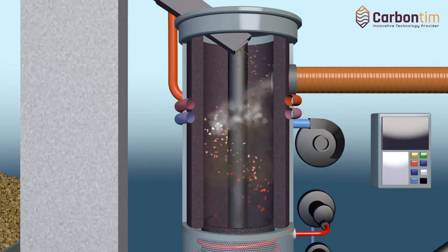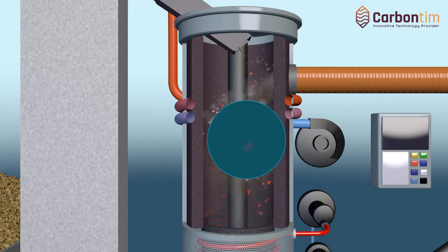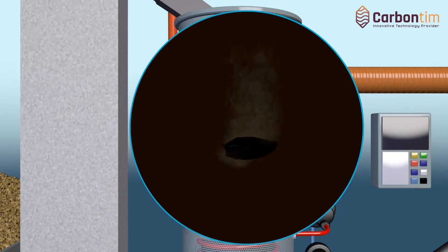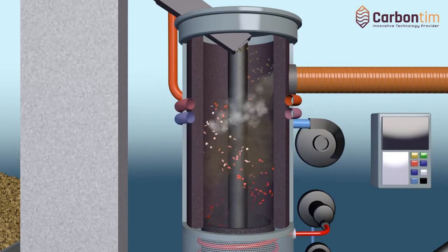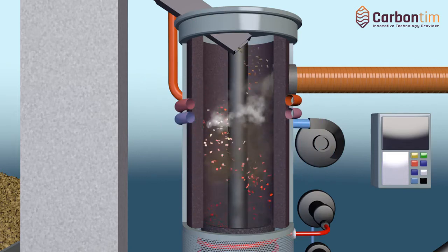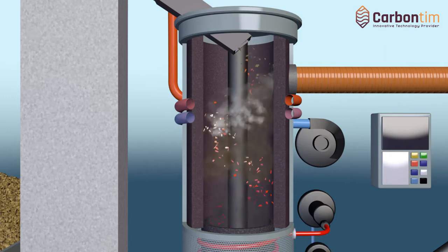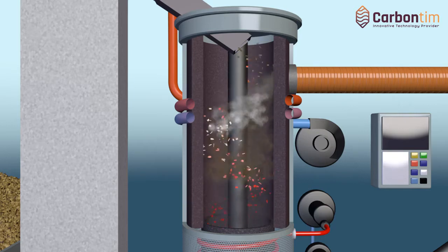The carbonization process. Dried and degasified biomass is treated with high temperature. This process results in the quick concentration of elemental carbon and the disappearance of the fibrous structure, improving its grindability. Depending on temperatures inside the reactor and the duration of the carbonization process, the ready material can have a calorific value in the range of 21 to 29 megajoules per kilogram.